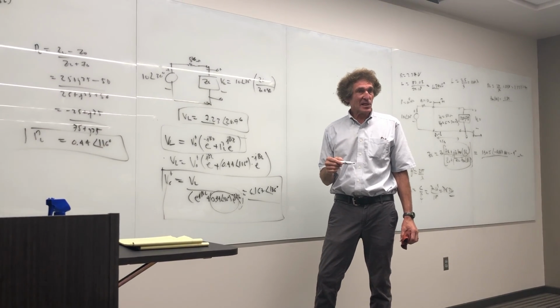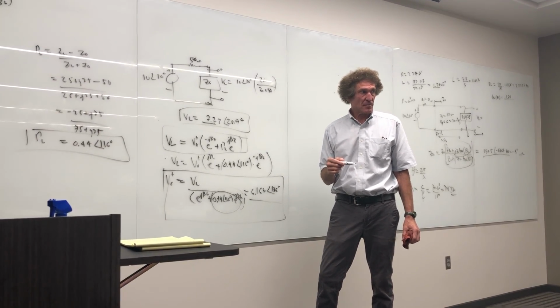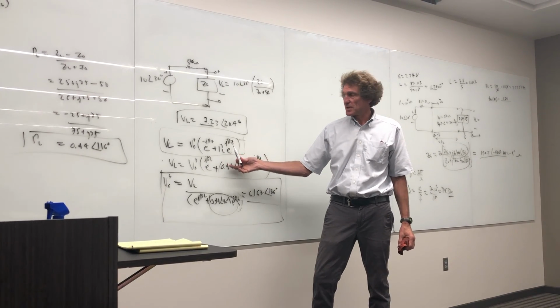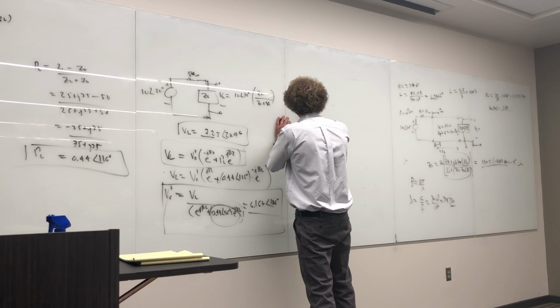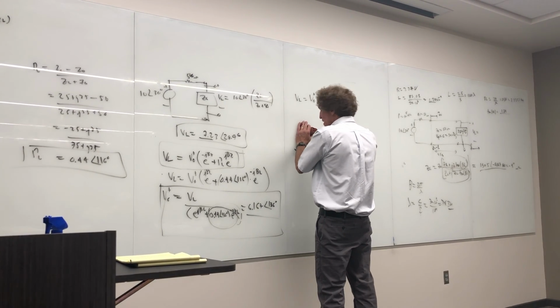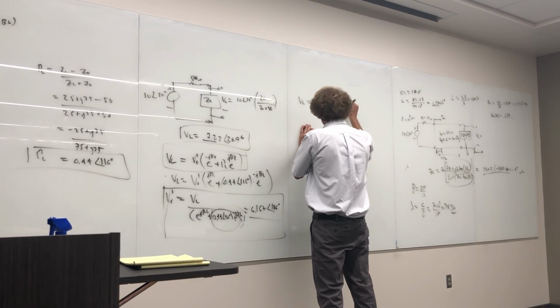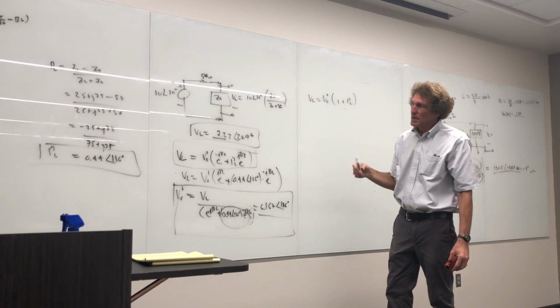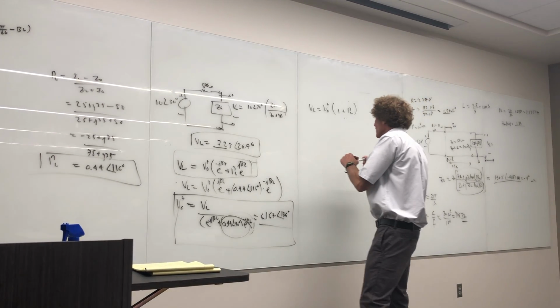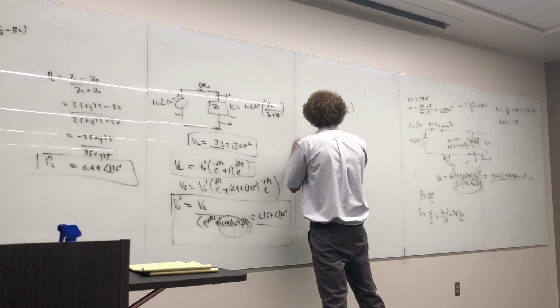So where is the load in terms of Z? So we would put in 0 for those values of Z, and now you would see that the V at the load would be V0 plus, and it would be 1, right? Plus the reflection coefficient. Right? Your reflection coefficient is 0.44 at an angle of 116. Therefore, what is VL going to be?